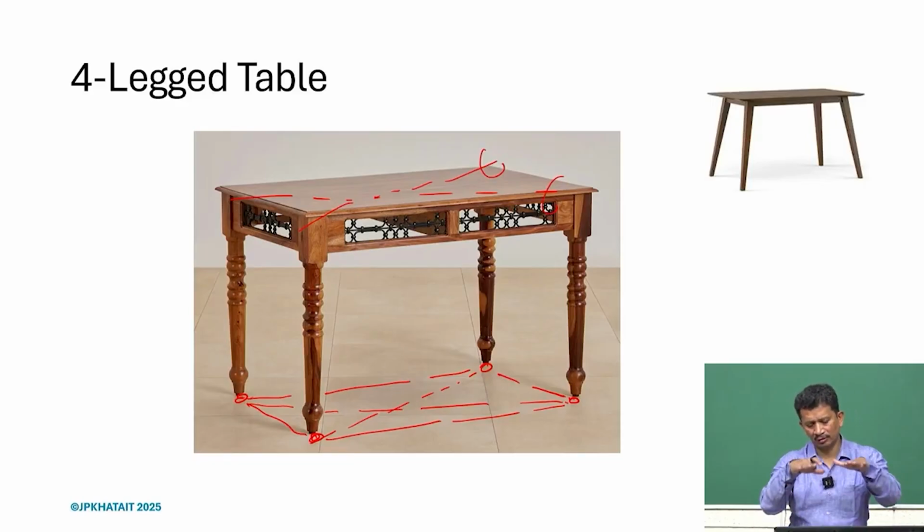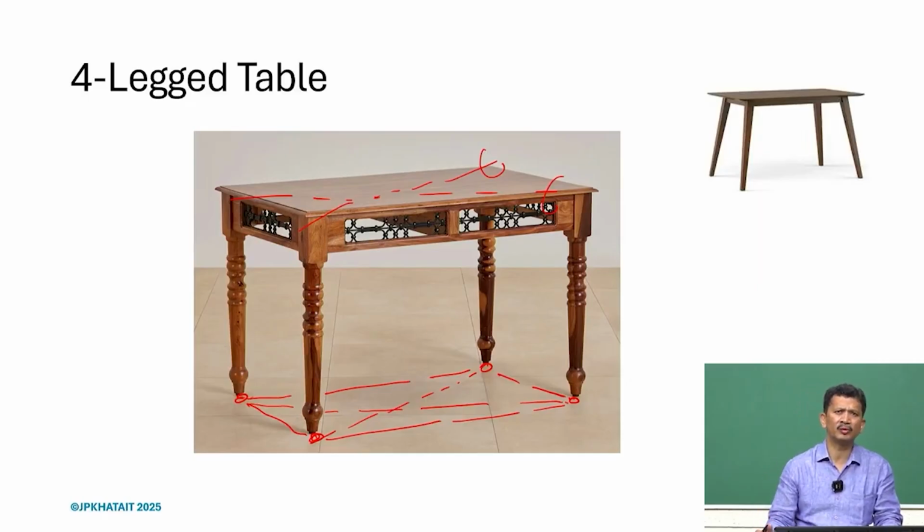So the moment the tabletop is compliant, it has diagonal degrees of freedom, it may be fine, because when we move it to a different location, it deforms and takes the shape of the surface. But because of that, the top surface now gets deformed, and it means anything we attach on top of the table will also get affected. The measurement, everything will get affected because of that deformation. So we should be aware of that.